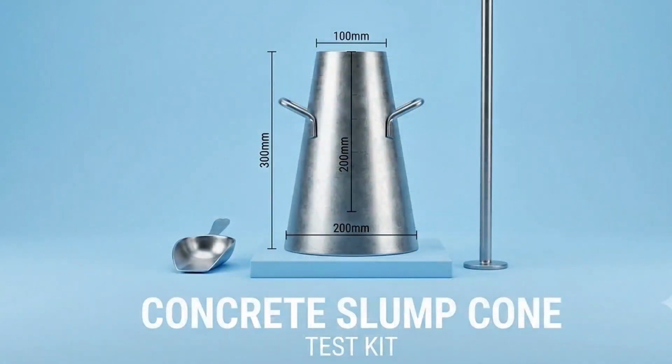A concrete slump cone measures the consistency and workability of freshly mixed concrete. The cone is filled with concrete and then lifted vertically. The amount the concrete settles, known as the slump, indicates whether the mix has the proper water content for the intended application. This simple test helps maintain concrete quality on construction sites.